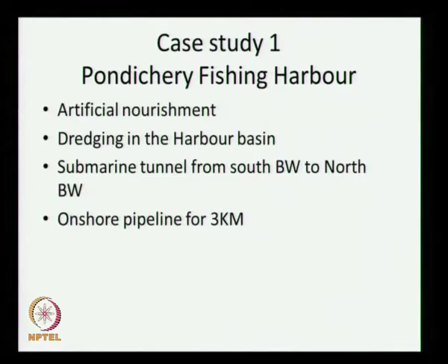As I told, it should be done preferably in the non-monsoon season, starting from December 15th and completed before March 15th. They are not carrying it out every year because of funds constraint, but when they have done it, they have seen that it is making the shoreline stable on the northern side, preventing it from erosion.